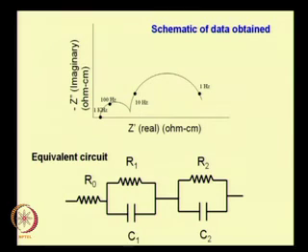It could be used in a variety of ways, as I just showed you with this kind of approach where you get data like this, some actual data, where each point, please remember, I have just marked some numbers here, each point here represents the impedance that was demonstrated by the sample at that specific frequency. So throughout this curve there are thousands of points; at each point one particular frequency of AC signal was sent through the sample and the real and imaginary impedances were recorded. Okay, so you get a complete curve like this, fine.